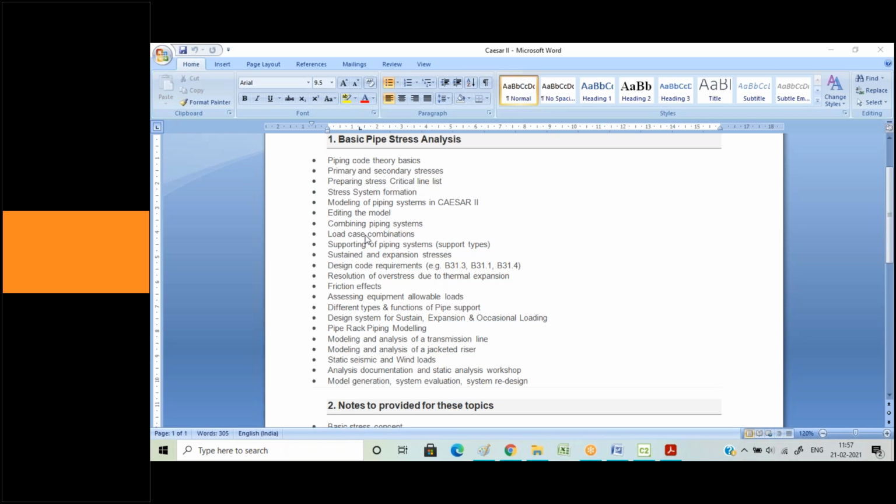So that lock pin basically helps the spring behave like a rigid support when it is not operational. When the line is in operating case, the line will tend to move either downwards or upwards. So accordingly, the lock pin has to be removed, and in a certain number of hours, your spring will accustom itself to the movement of the line.